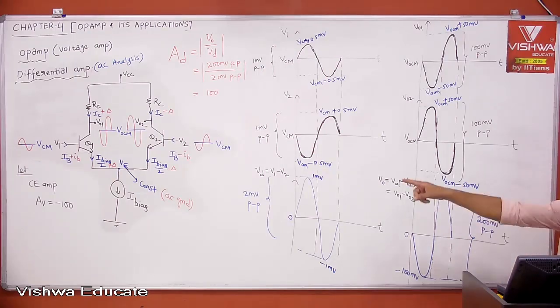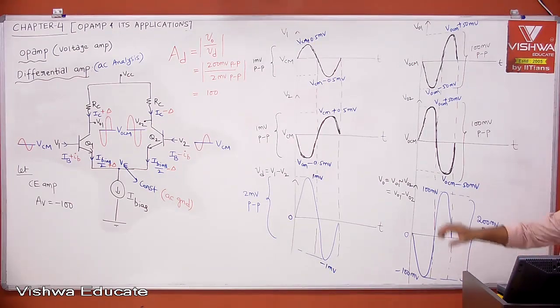Therefore, tell me, do we have any capacitor? No, right? Except the current source, maybe it will be replaced with a practical current source or a resistor, right? There we don't need any capacitor. Because of the differential point at the emitter and applying inputs in a differential manner, we don't need any bypass capacitor.